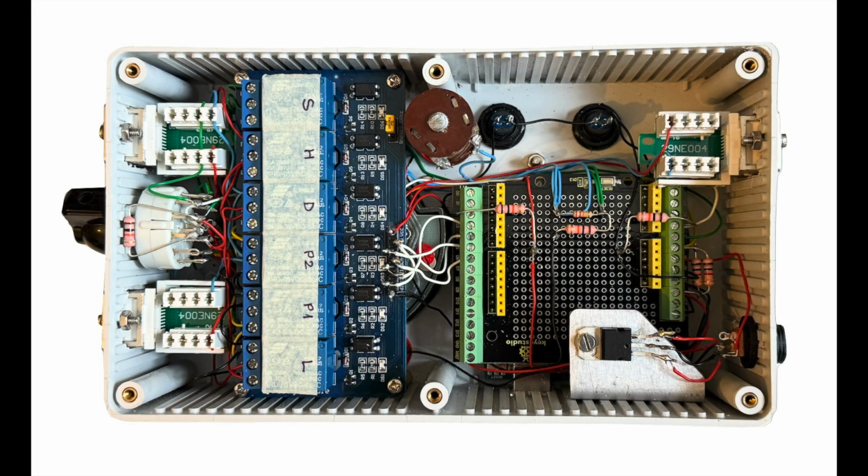Here is a view of the wiring inside the converter box. On the left are the phone selector switch and the RJ12 connectors for the telephones. Next to that are 6 single relays. The Arduino itself is hidden underneath the black screw shield. At the bottom right is a 7805 voltage regulator that provides power to the relays independently of the Arduino. The supply of the box itself is by a 9-volt adapter.